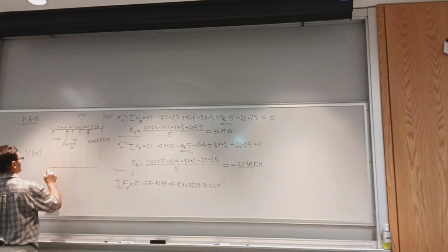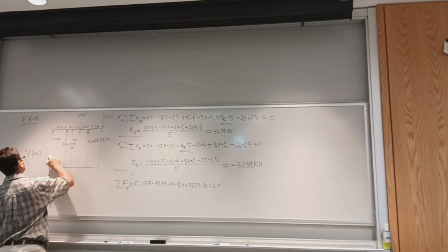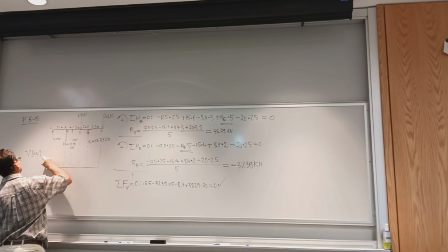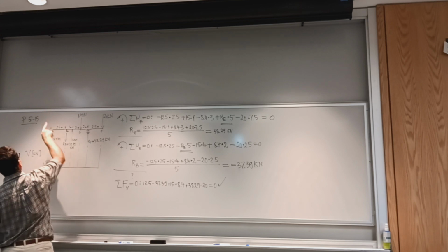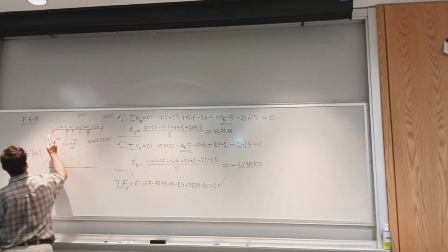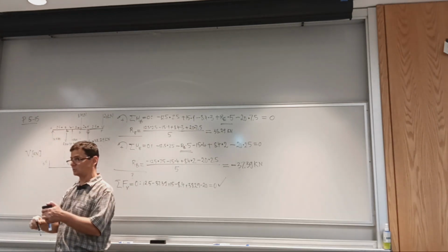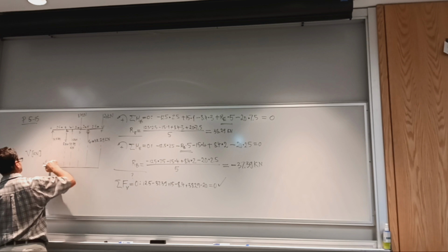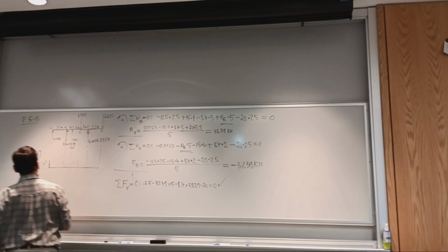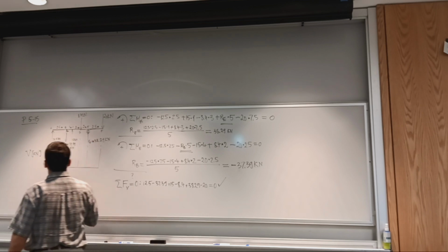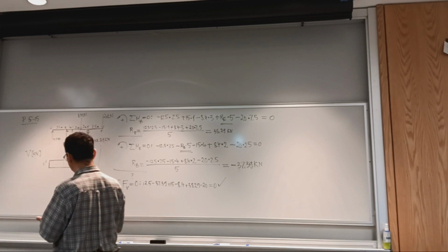All right, so a straight line, that's the neutral axis of the beam, really, and I begin with a 12.5 kilonewton positive, because it's up. Internally, once I move slightly right of point A, I see a shear that is downwards. That's the positive. But an external force upwards causes a positive up jump of the shear diagram.